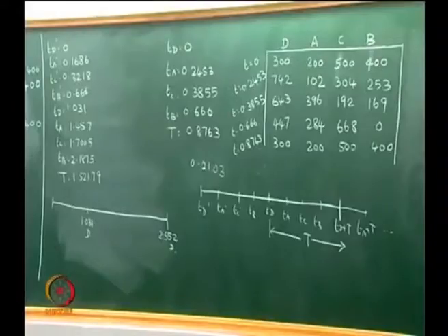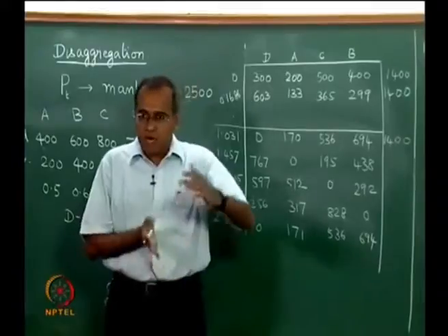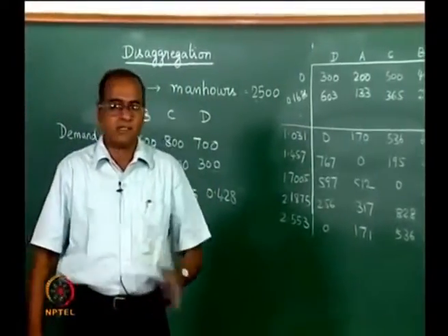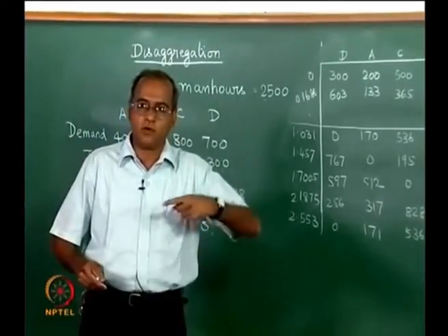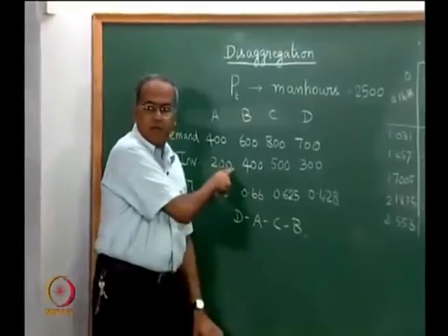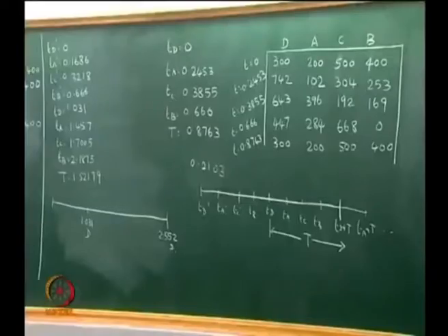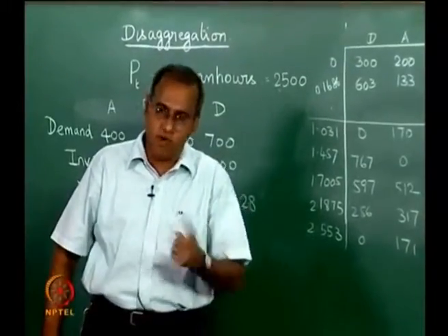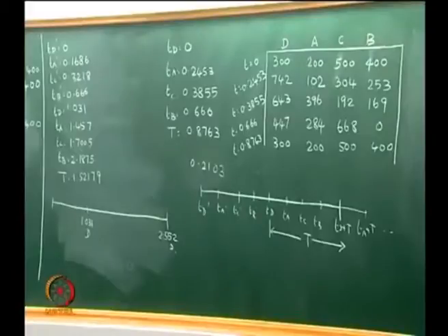So even though the objective is to maximize T, in some sense we are not trying to do it at the expense of today's thinking. The model essentially tries to maximize T, but the model still takes us to something that is practical and something that is the requirement of today, which is to minimize the cycle so that we are able to have shorter runs of larger variety. The answer lies in the amount of inventory that we keep on hand. So automatically if these values are smaller, the R values will become smaller and the cycle time will be smaller. Similarly, if the changeover times and changeover costs are smaller, then it is possible to have more changeovers, bring in more variety and produce at shorter runs and smaller T.